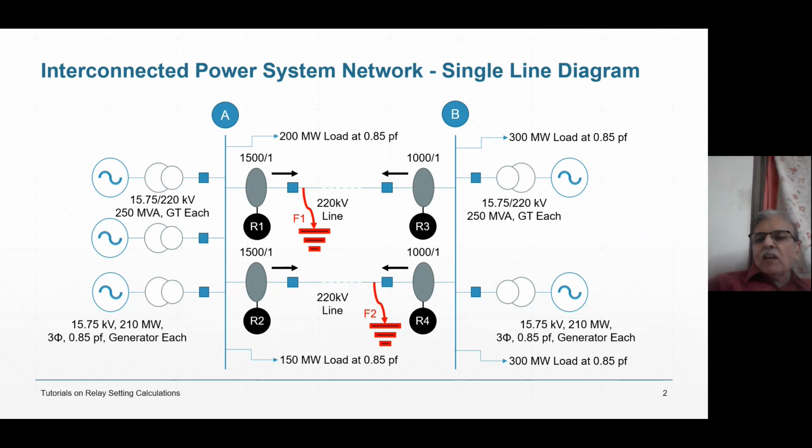At bus B, 600 megawatt load is there, but the generation is less. So obviously you will have to do some load shedding. So there is no use of taking two line contingency here. If there are 50 lines, then you can think of two line contingency, which no people have done.